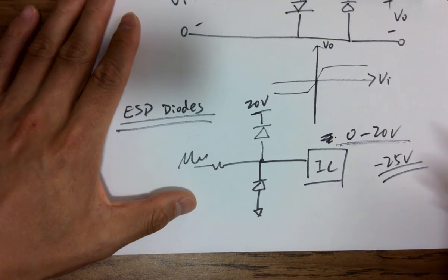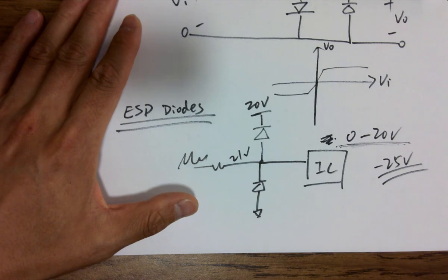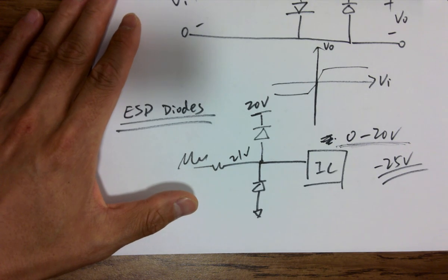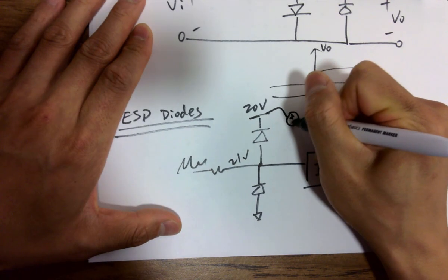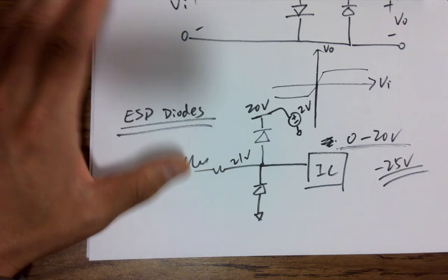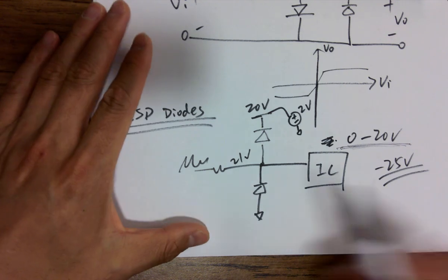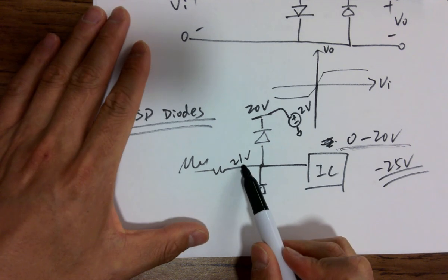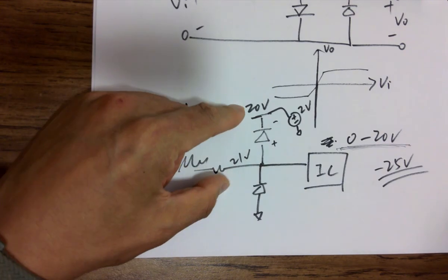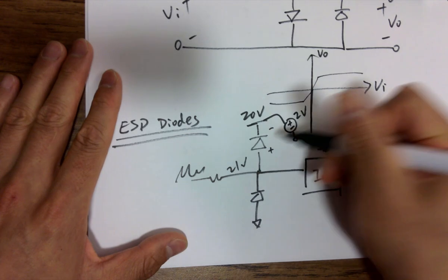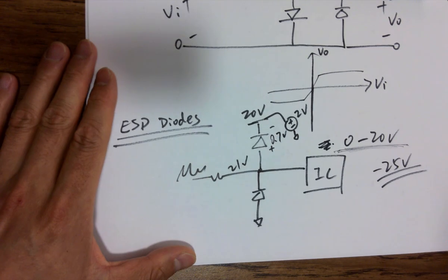Think about that. So what if I'm getting 21 volts? What's going to happen? The top. So 20 volts means what? Agree with that? Yeah. 20 volts is the power supply, 20 volts, right? If this guy is 21 volts, what's going to happen? It's going to become forward biased, because it's larger than 0.7 volts. 21 minus 20 is 1 volt, larger than 0.7. So what's the drop across this guy? You're saying 1 volt. What's the drop? 0.7. 0.7, right? Fixed.